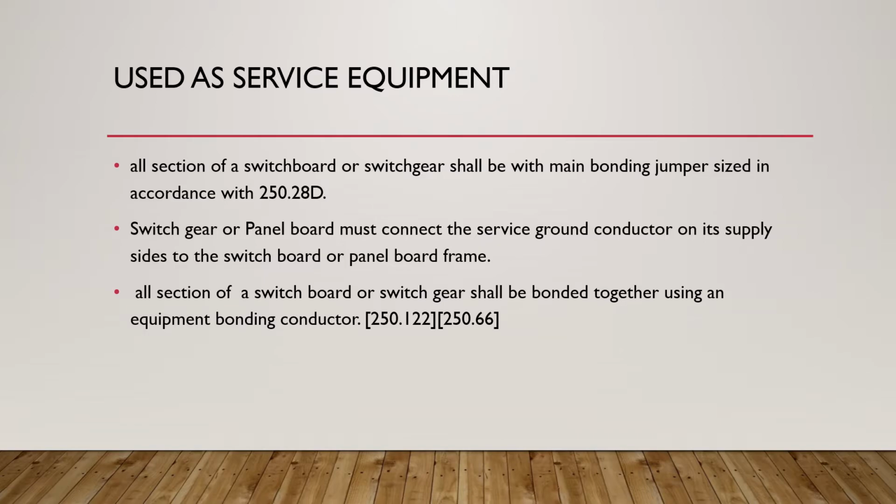All right. So these equipments, when used as a service, should establish the main or supply bonding jumper, right? And all sections of the switchboard, we should establish following Article 250.122 and 250.66. All right. So that is the rules for using equipment as service.